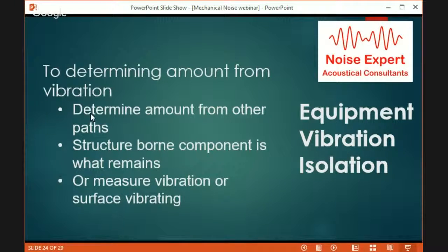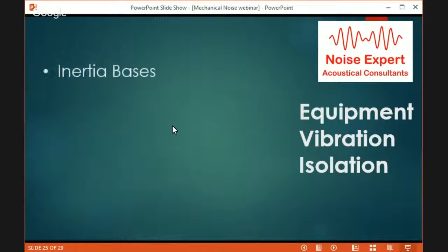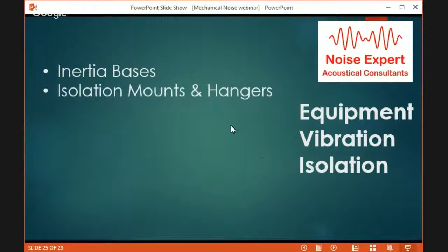Follow the vibration isolation guidelines for the equipment that's being used. And the stiffer the roof system, the better. The closer they're located to structural components, the better. So some of the options you have: inertia bases, and again, the ASHRAE manual. A lot of times we use Mason Industries. They're very helpful in guiding what is required.